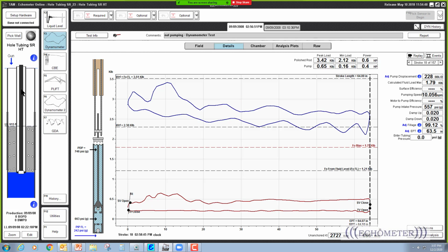The rod string is in air down to the hole, and it weighs more. So when we subtract off weight of rods and fluid at the pump, it doesn't go to 0, and it would normally. So that's a big advantage of the horseshoe load cell, that it actually measures the actual loads, and you can compare those to these reference load lines, and maybe understand a little bit better than using the PRT. But the PRT is so fast and easy, I'd still use it all the time unless I needed to use a horseshoe load cell.